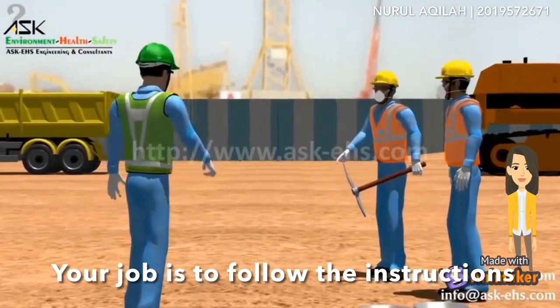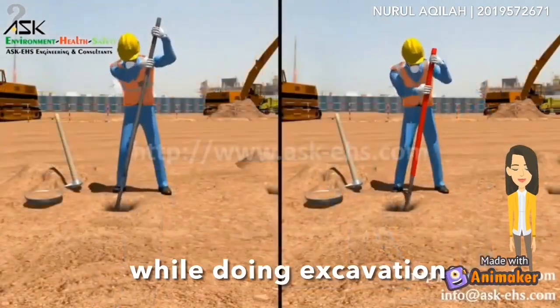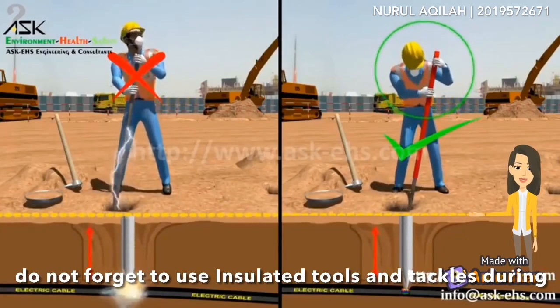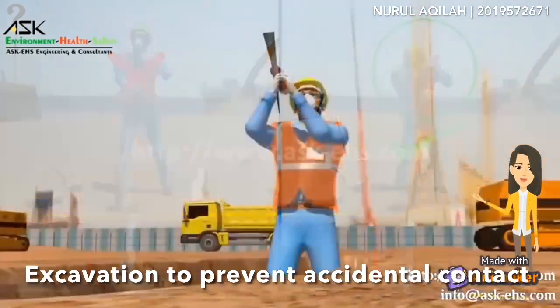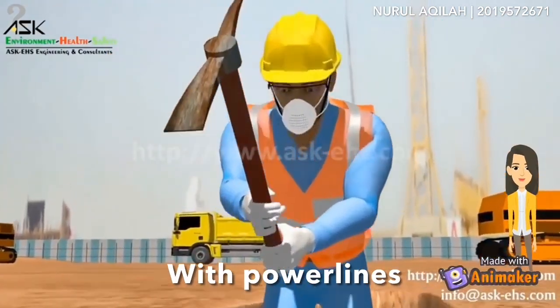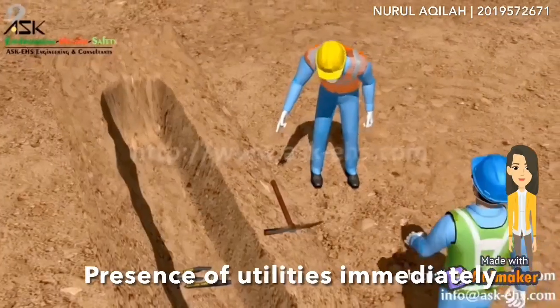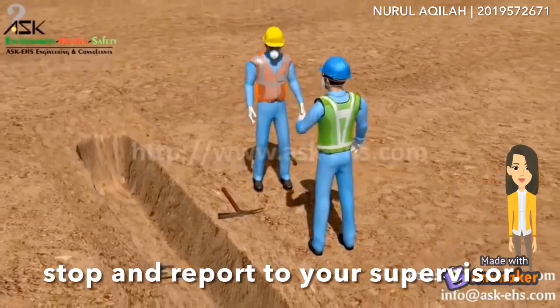Your job is to follow the instructions of the supervisor carefully while doing excavation. Do not forget to use insulated tools and tackle during excavation to prevent accidental contact with power lines. Still, if you come across any symptom of the presence of utilities, immediately stop the work and report to your supervisor.